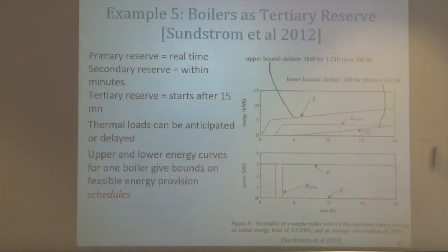So if I do a set point of the boilers that is just in the middle, for example this red curve here, if I'm on this curve at this point, by stopping a number of boilers, I can start delaying the curve, so I can move closer to this one here, or I can start more boilers to come here.